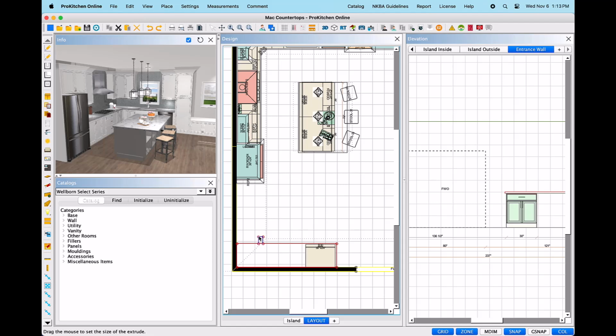Then, move the mouse into or beyond the existing countertop, creating or reducing depth and over to the opposite end of the edge to control the width of the extrusion. The blue lines will denote where the extrusion will appear and give you a preview of what the new countertop shape will be. Once the extrusion is your preferred width and depth, left-click to secure.